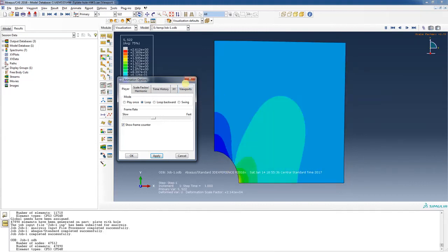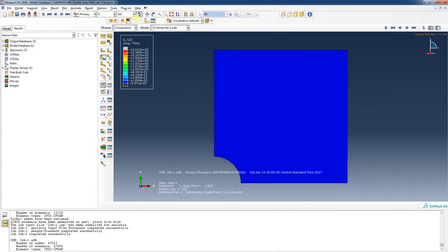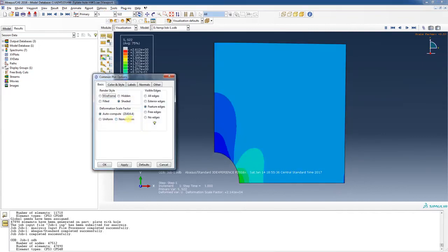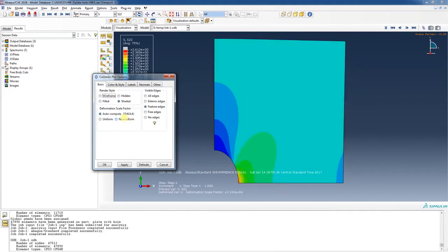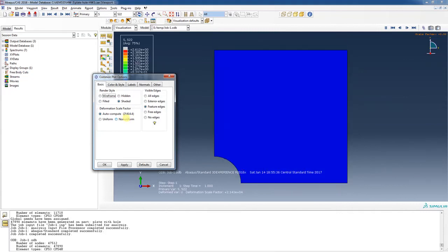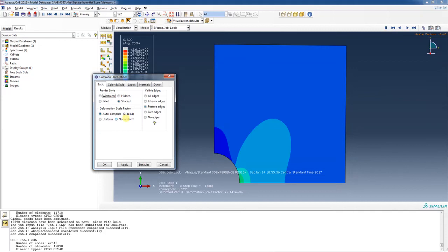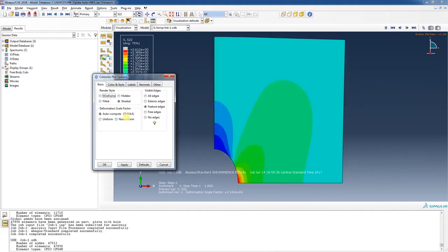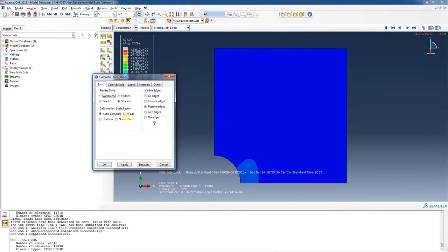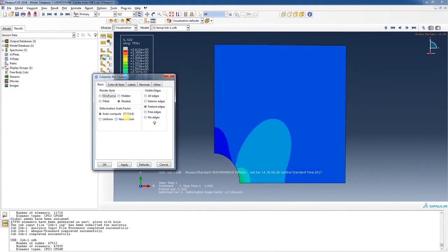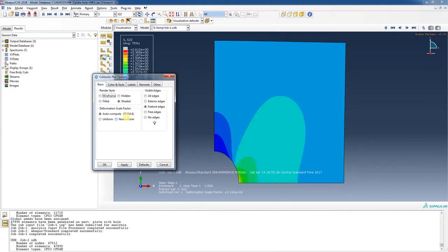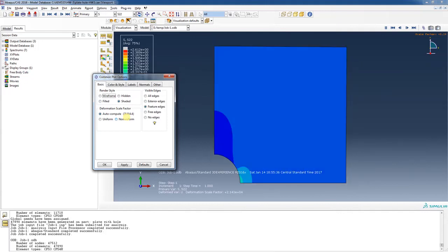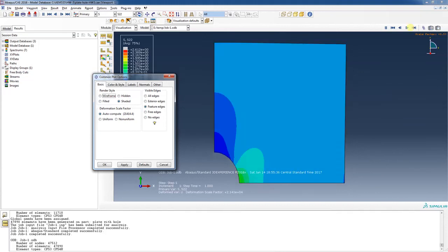This hole is getting stretched out. Now this is an exaggerated deformation. It's quite large. We're not applying a very big stress on this, so the scale factor for the deformation is 21,414. That's a huge thing. But it's always handy to animate this with an exaggerated deformation, so you can see if anything unusual is happening in your mesh. Let's go to the last frame.